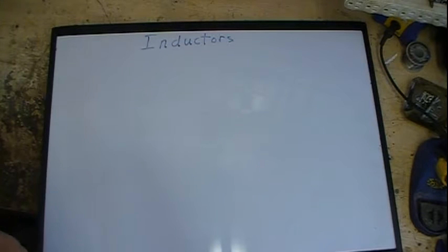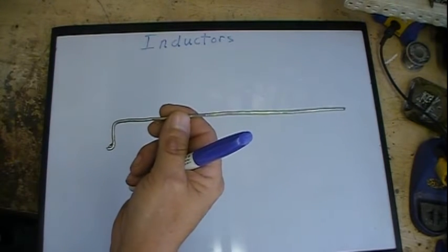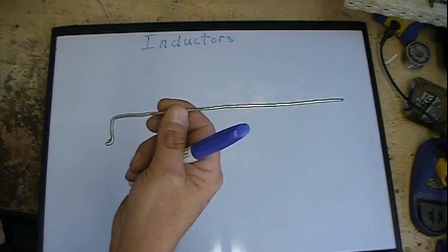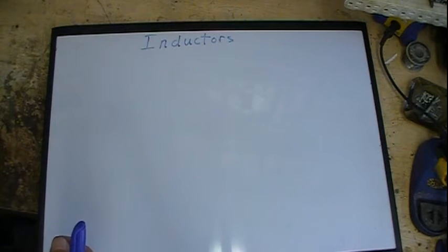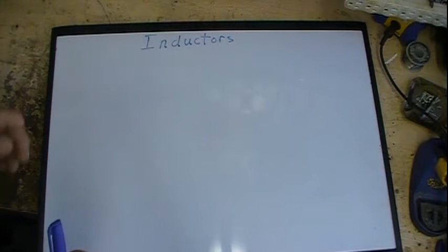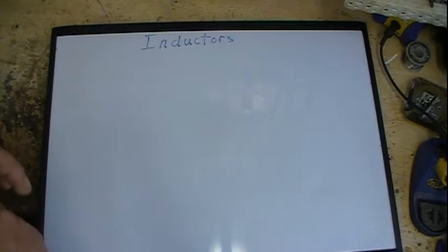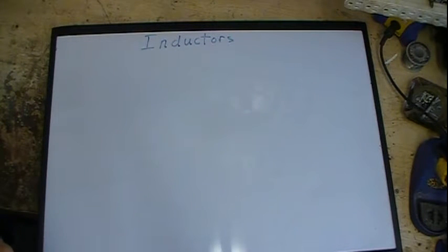First of all, what is an inductor? Well, simply put, that right there, hooked into a circuit, can be an inductor. Just a piece of wire. At ultra high frequencies, basically your inductors are nothing more than either a slightly curved or possibly even a relatively straight piece of short wire. So let's look at this a little bit.